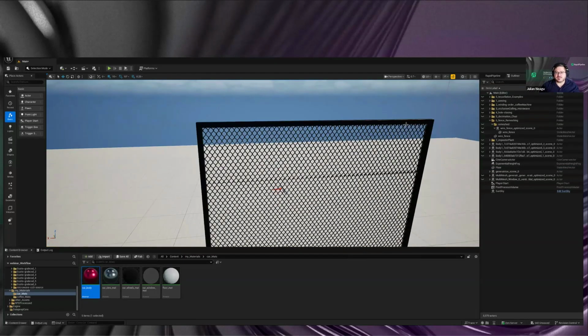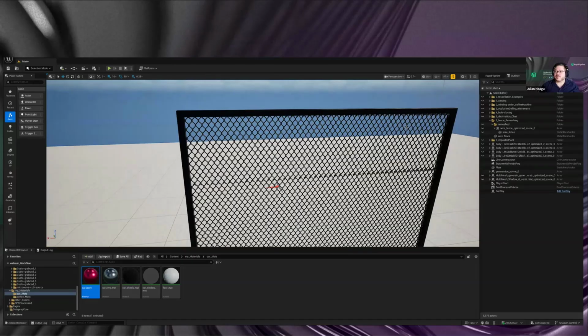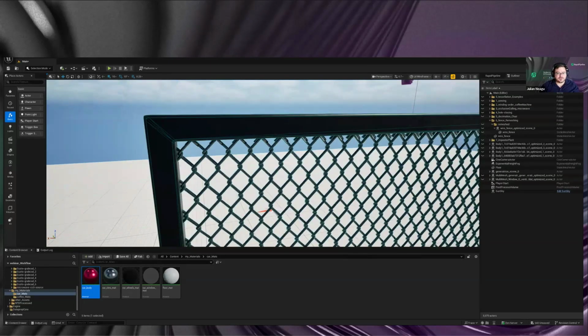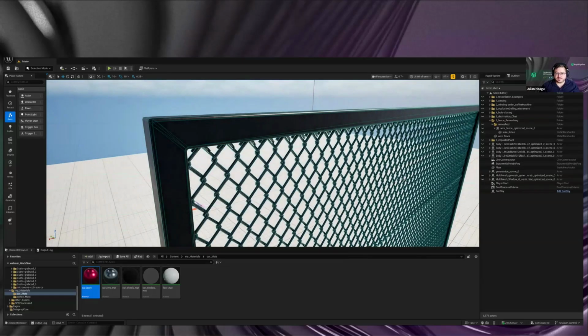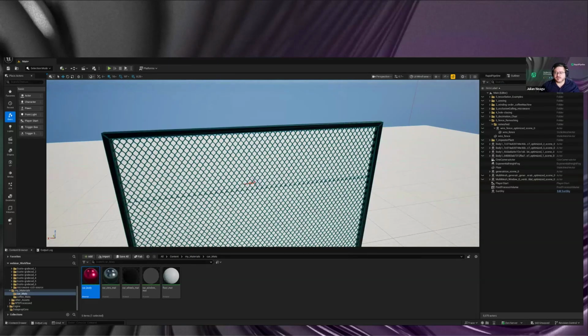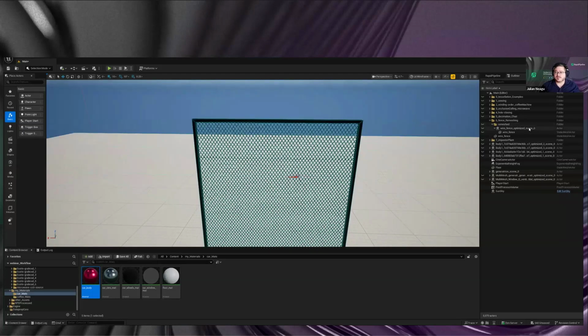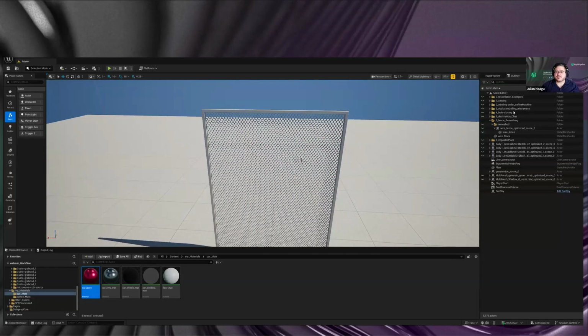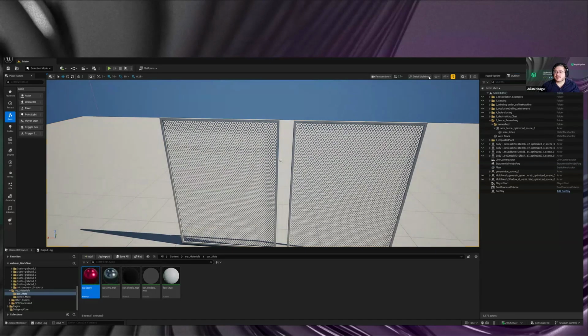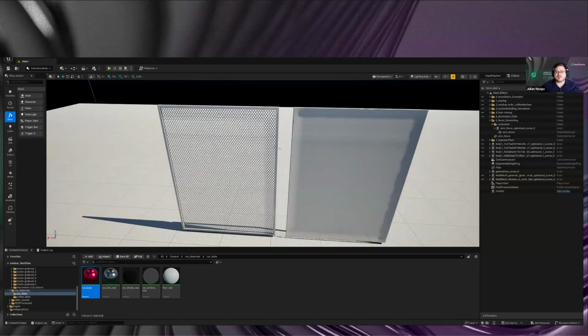So this example is a very interesting one where we're using all these features, the shrink wrapping, the baking, but we're also using alpha baking. So if we go here on the wireframe resolution, you can see a view mode here. You can see this little wire in that frame. This is all meshed, and basically this is something we, in this case, want to completely remesh. We want to get a completely low resolution representation. So if I, for example, switch to the detailed lighting mode and I'm blending in that, you see other wireframes here, and you see it's lighting only. Yeah, so lighting only mode.